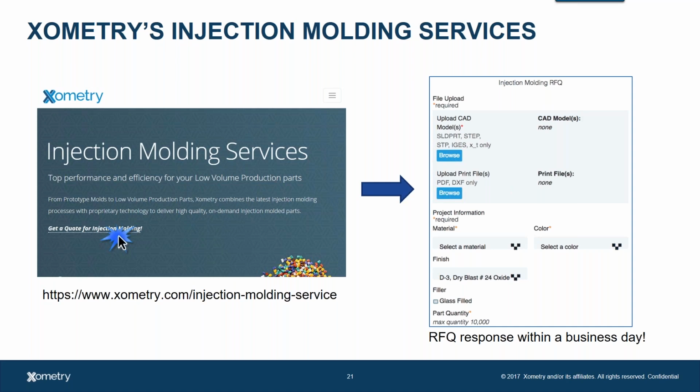And if you are looking at quantities that are between like 1 and 250 units, I may come back and ask you a couple questions because we have some options with 3D printing and with urethane casting, maybe a better option for that. Really, a sweet spot for injection mold, I actually think starts at 500, but really 250 is probably a good start point on the minimum quantity to get the bang for your buck when you're actually doing injection mold services. And that's because you have that initial upfront tool cost. So the parts may be cheap, but you're still paying for that tool there.